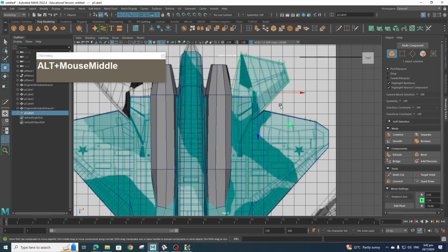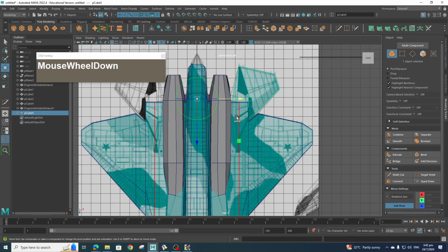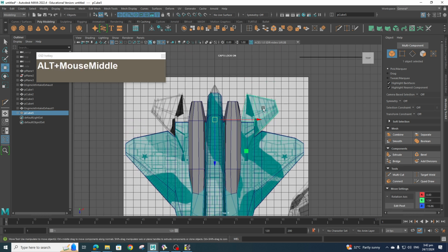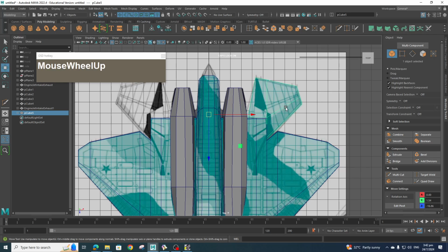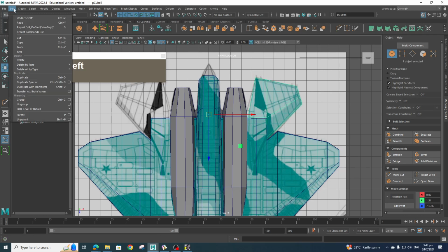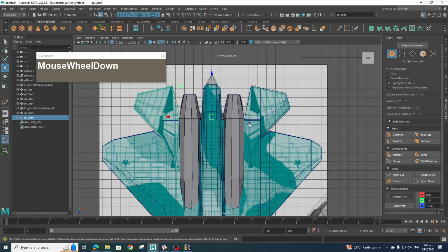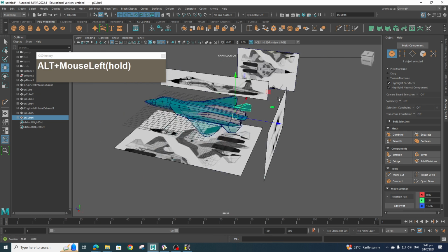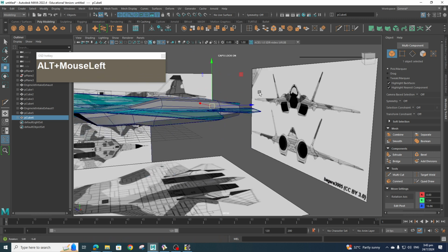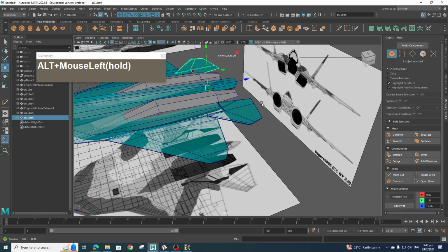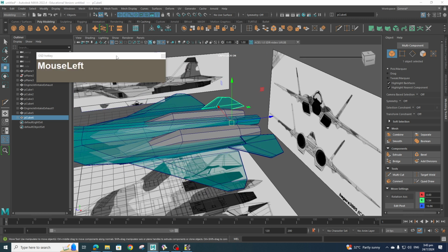Using the same technique, press D and then hold down X. And press D again to get out of pivot point manipulation, rather. Then Edit, Duplicate Special. We have the other tail fin done. Okay, so now we need to have our horizontal or vertical stabilizer.